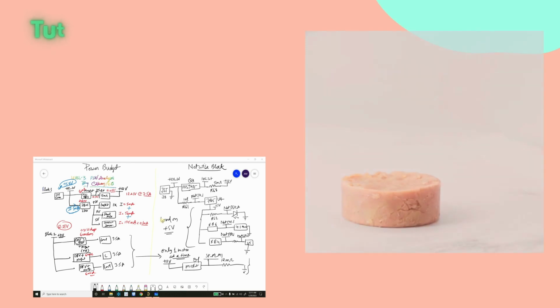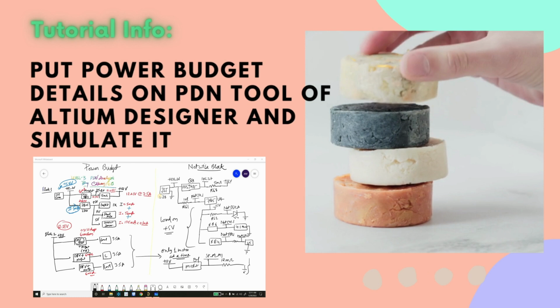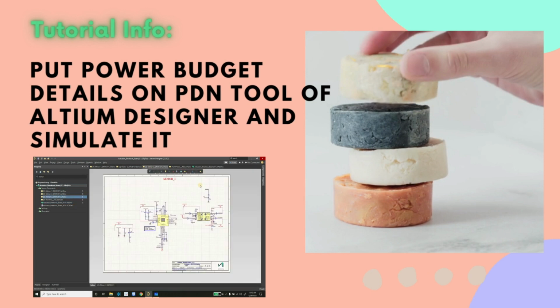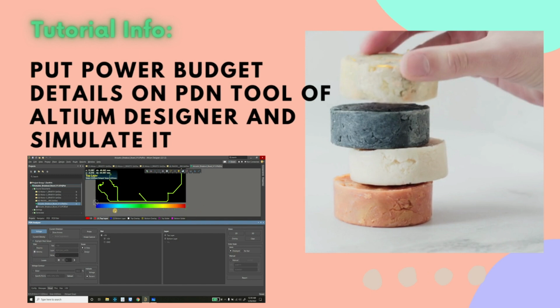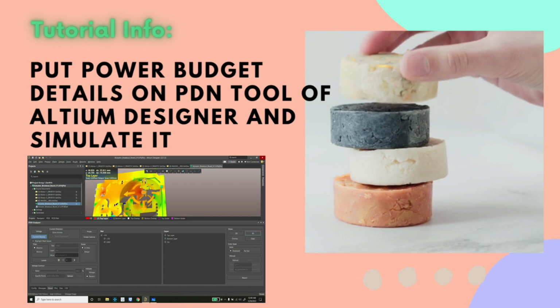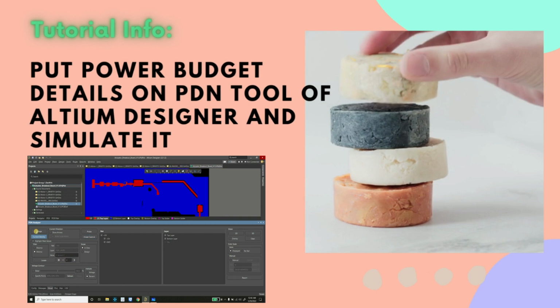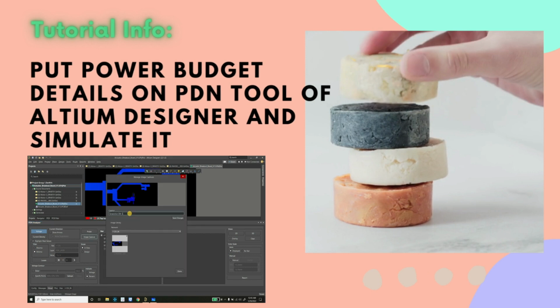Now in this video we're going to understand the net-wise block diagram which we'll create from the power budget and schematic of our project. After that we'll put all this information from the power budget and net-wise block into the PDN Analyzer tool, and then we will go for the simulation. After simulation we'll analyze the results, and if there are any issues or fails, we'll implement those changes back to the design, and we'll keep doing that. It's a simple loop process. We keep doing that until all the test cases pass.